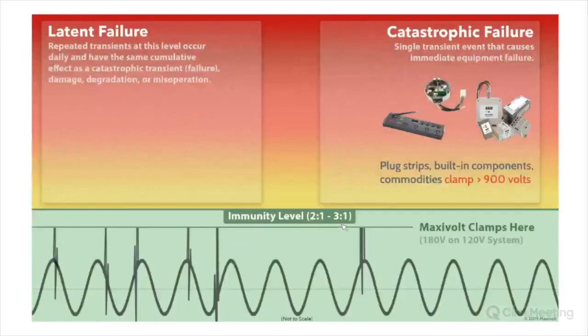So just another quick clarification here. One of the things that's interesting about this whole idea of voltage protection is this industry doesn't use the term voltage protection very well. In other words, when you buy an SPD, a surge protection device, most of the time you see this parameter that talks about surge current rating. Well, to the equipment, is it the current that's the problem, or is it the voltage that's the problem?